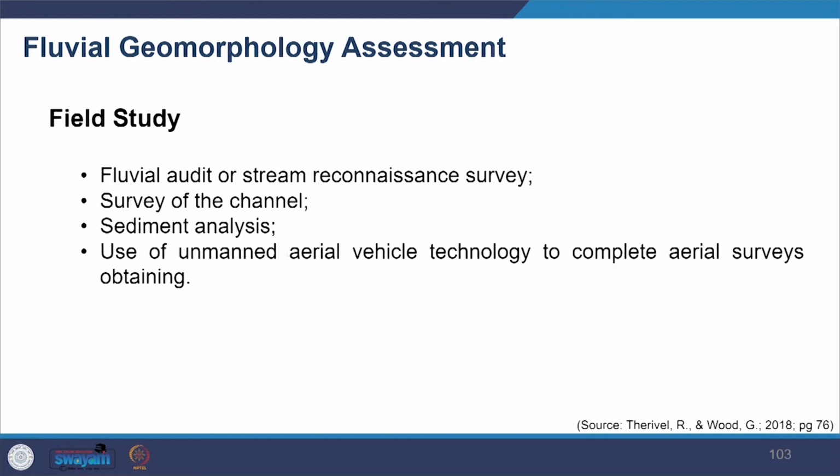The field study in this particular case would involve a stream reconnaissance survey to collect information on channel size, survey of the channel to obtain accurate slope and bankfull characteristics, and to record geomorphological features. Sediment analysis might also help. Increasing use of unmanned aerial vehicle technology like drones can also be used here.